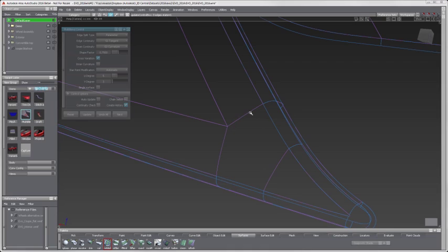Start by selecting an edge, and then Accept. For a 5-sided surface like this, I will have to select and hit Accept 5 times, so I typically use the spacebar. I can see that I have enclosed my opening, so I'll click the on-screen Done button. Hitting the spacebar again builds the surface.